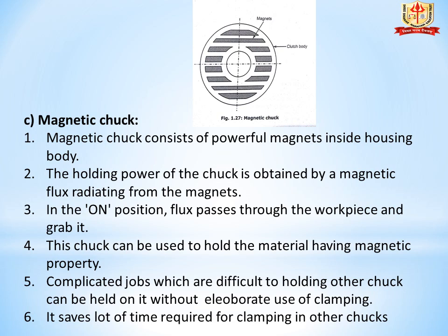Fourth point, this chuck can be used to hold material having magnetic property. Fifth, complicated jobs which are difficult to hold in other chucks can be held on it without elaborate use of clamping. Sixth, it saves a lot of time required for clamping in other chucks.